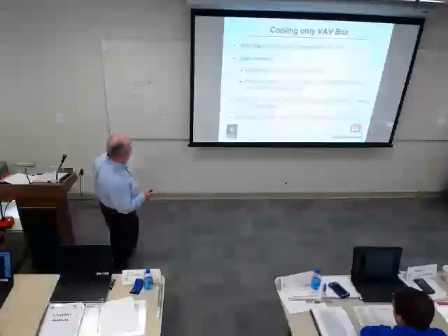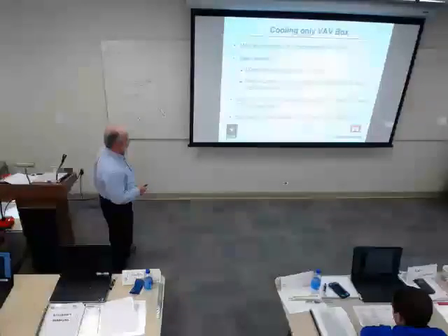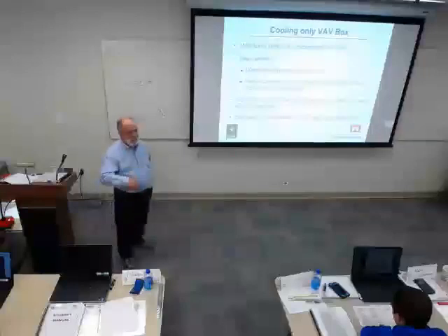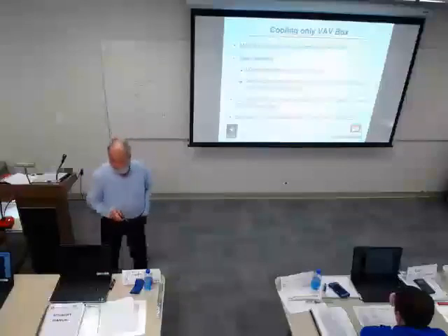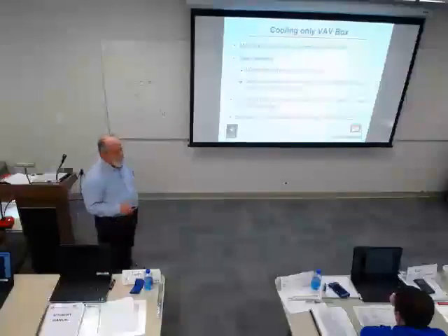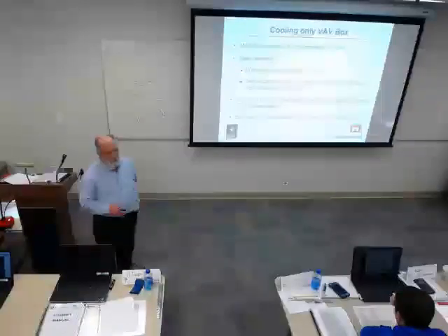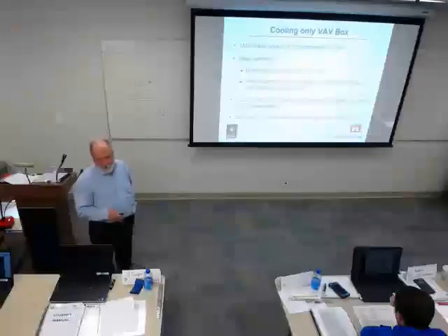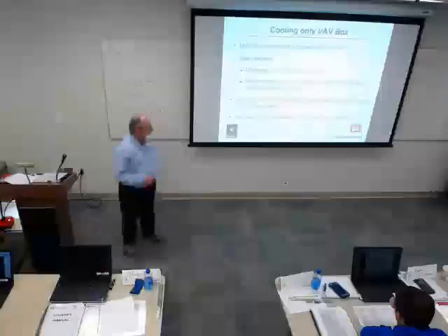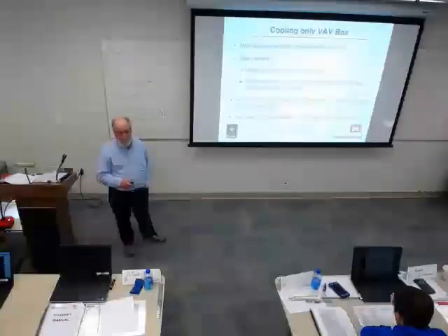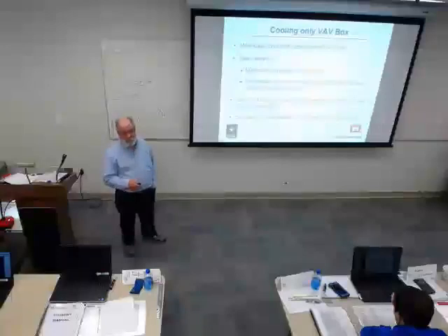Okay, let's see here. One of the problems we have now is the belief that if a room is empty, and this is a philosophical thing, so I won't dive into it too much, we have a minimum airflow. And very often that minimum airflow isn't effective when the room is totally empty and all the lights are off and the equipment's shut down. And when that is true, we can subcool the room and we have no cooling. And so in that case, we very often have to put in reheat, because reheat is better than cheese.